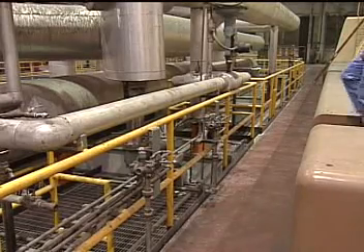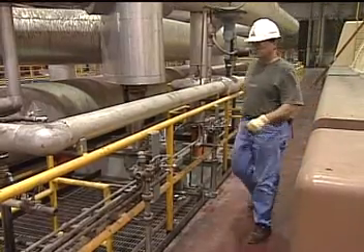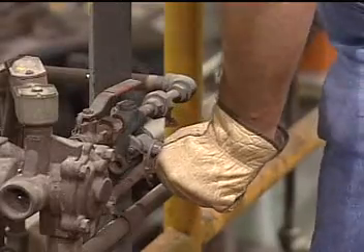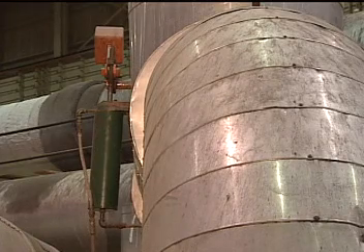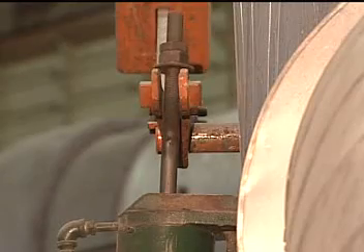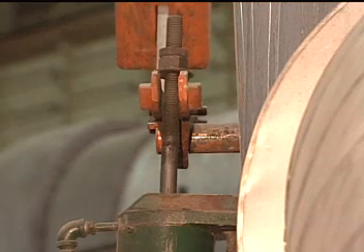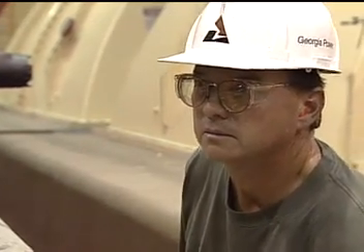Some non-return valves have air assist actuators to help ensure closing. You'll need to check the air assist actuators to be certain that they're operating properly. To do this, operate the controls that move the actuator and observe whether the operating arm is free to move.